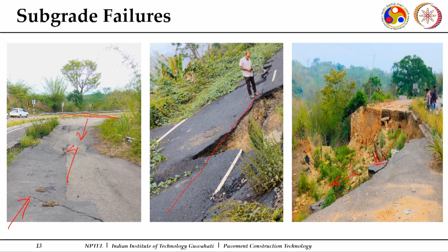You can see this is a bituminous bound course, you have the granular courses, and at the bottom you have subgrade courses. So you should not feel that pavements will not fail in this big manner. You can see only some cracks coming up, some depressions coming up. No, this can happen, and when it comes to hilly regions, it becomes even more risky. So subgrade, the foundation of our pavement structure, plays a very, very important role. With this, we'll end this talk here. Thank you so much.